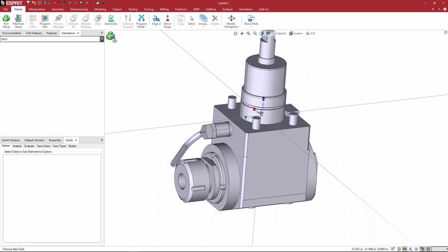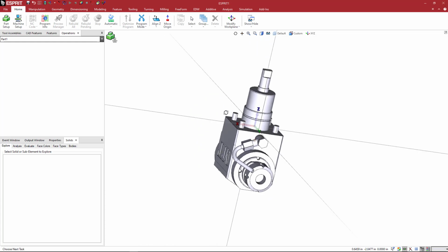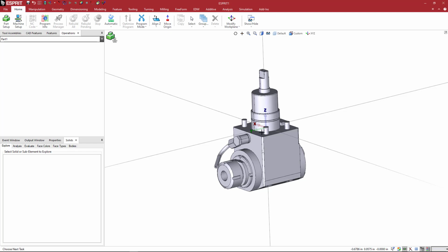The other thing is the x-axis. We want the tool, the holder, when we load it on the turret to be oriented in rotation around Z, facing the main spindle. That way, if I want it on the sub, I just put in 180, or if I load it and it's going to be working on the main, I don't have to do any rotation. So we see the X. This is the vector that points toward the main, the X. So what I need to do is rotate this -90 around Z.